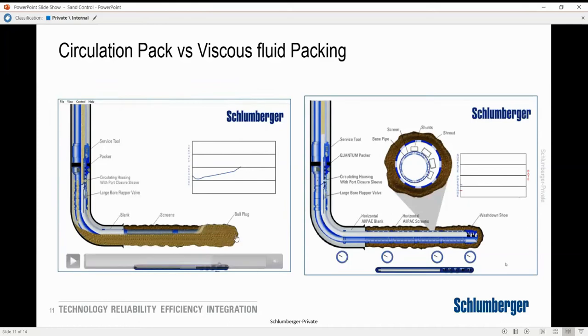As soon as the alpha wave is packed and over, the beta wave is formed. The gap above the first wave is covered by the beta wave, where your pressure goes high because the area of the opening for flow is reducing to the point where you don't have any area to flow back, and your pressure spikes. That's called the screen out, which means all the screen section has been covered with sand.